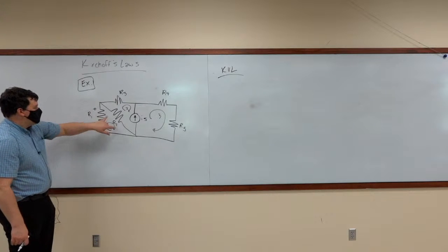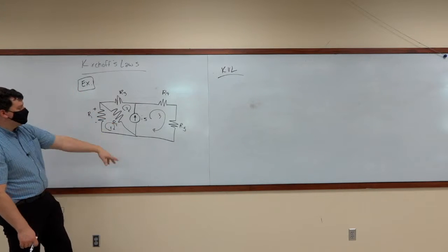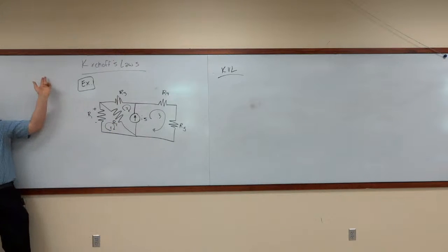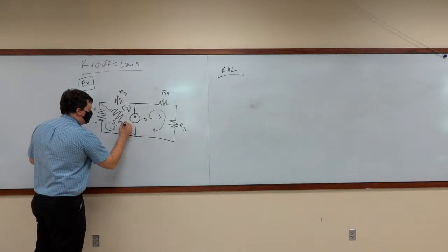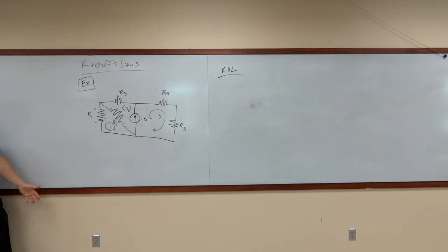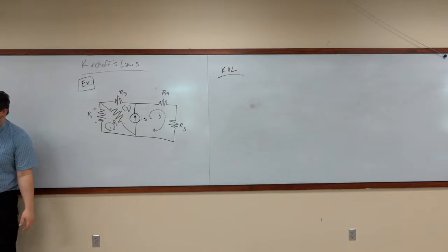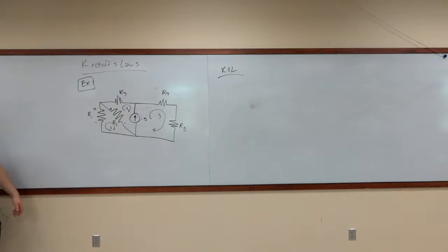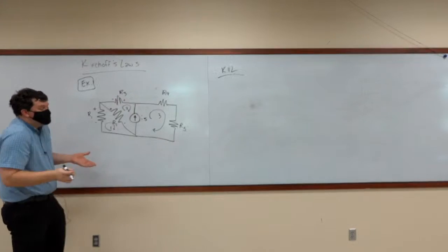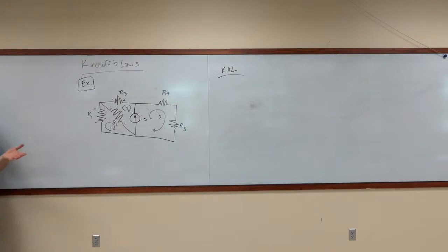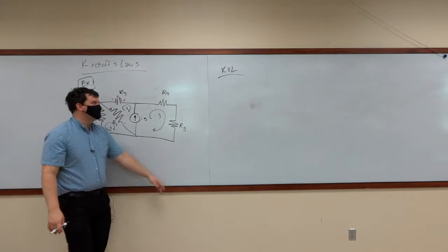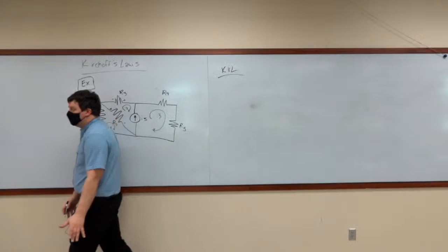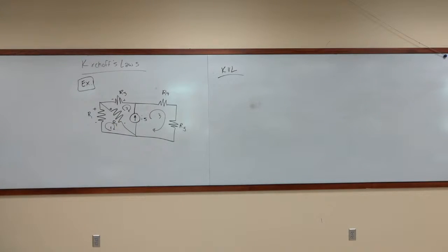Okay? What about R2? Is it going to be top left, or is it going to be bottom right positive? Top left. And then we'll do a negative down there. What about R3? Positive on the left or right? Okay, once again, if you get these wrong, it doesn't matter that much. We're initiating numbers because by drawing positive and negatives, it'll make sure that when we go to do KVL and KCL, we get our numbers correct. All that matters is that you're consistent. The way I teach all of my classes, number signs suck, but as long as you're consistent about them, we're in a good place.